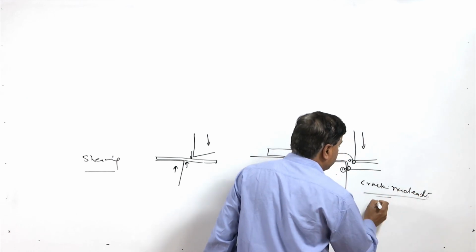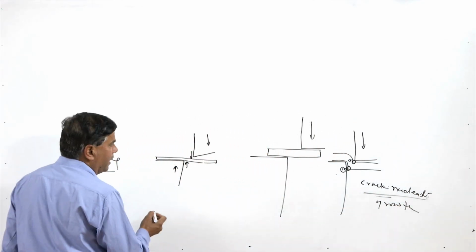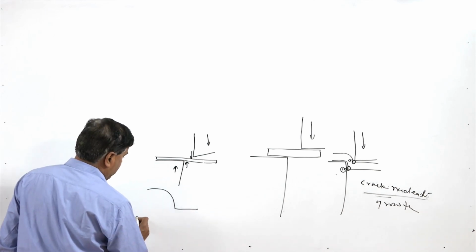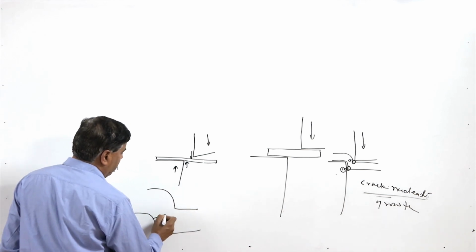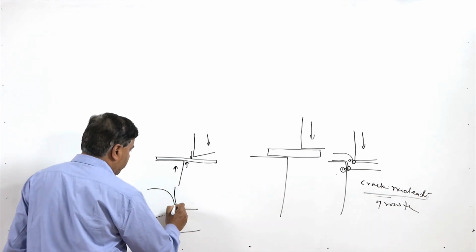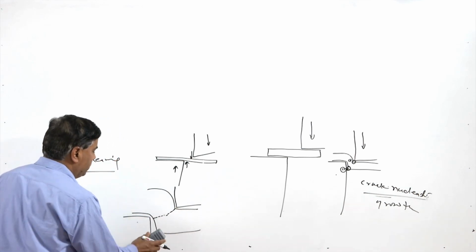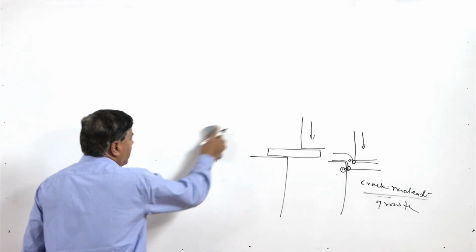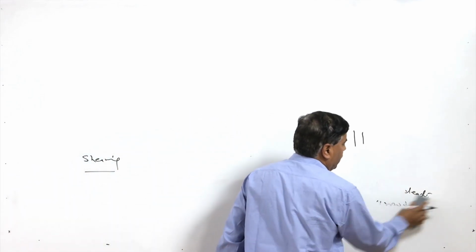Nucleation of the cracks and their subsequent growth leads to fracture and separation. When the gap between the blades is optimum, the cracks propagate from both sides and meet at the center of the strip, leading to separation under optimum conditions of clearance.